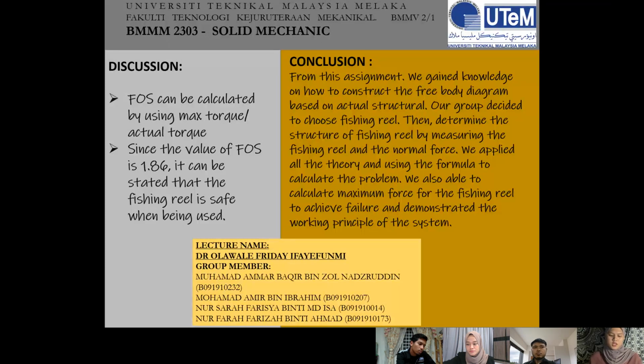Based on our project, the factor of safety can be calculated by using max torque divided by actual torque. Since the value for our project is 1.86, it can be stated that the fishing reel is safe while being used. That's all.